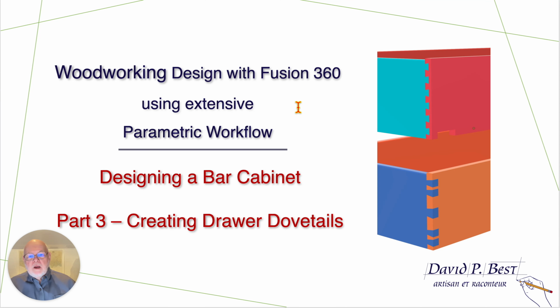Welcome back. This is episode 3 of our woodworking design project where we're designing a bar cabinet using Fusion 360 and parametric design techniques. In this episode, we're going to go forward from our last episode when we created a drawer box modeling system and add dovetails to the drawer boxes. I'm going to demonstrate two techniques. One would be for half-blind dovetails that are equally spaced, and the other would be for through dovetails that are unequally spaced. So let's get on with it.